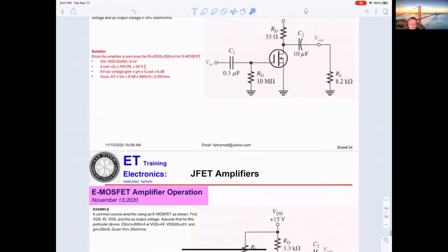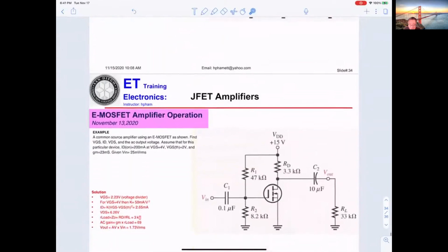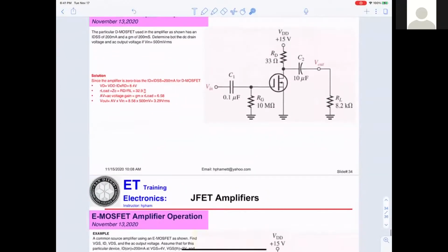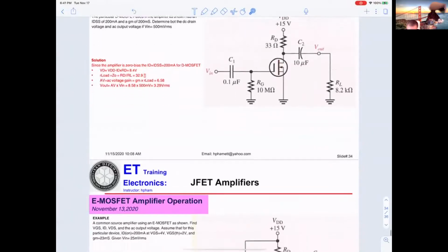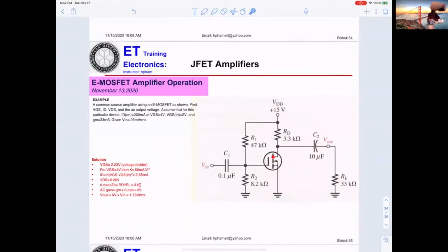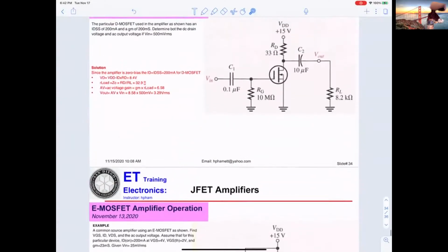See, the circuit looks the same, right? The voltage in is positive or negative? Now, the symbol is slightly different between the E MOSFET and the D MOSFET, with the broken line in the circle. Exactly, that is the key. You can see that is not a broken line, right? However, this one is a broken line right here. This is the symbol for E, and this will be the symbol for D.